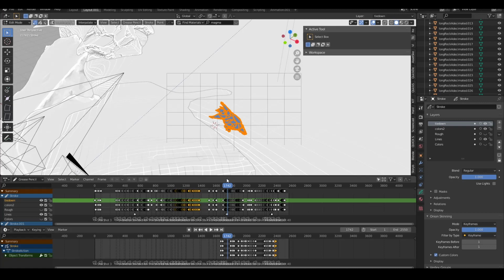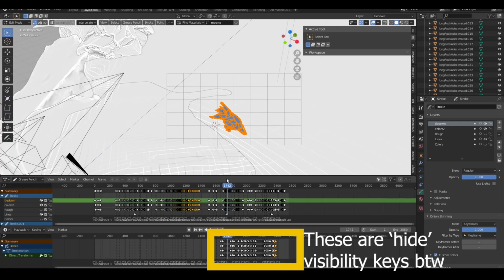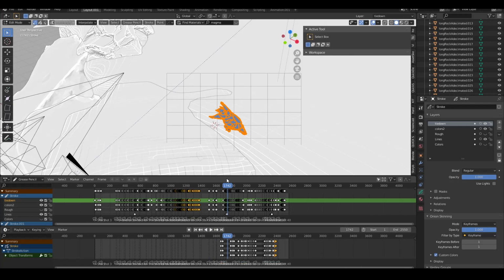Normally this was the kind of fight, wasn't it? You would have the object keys and then you'd have to move the object keys and then move the grease pencil. So in this one there are no object keys. If you want to move your artwork in an object-y kind of way, like in 3D space, then you have to grab it in edit mode and move it. I've got some ideas how to make this easier, but basically, edit mode and cursor mode, no object mode.